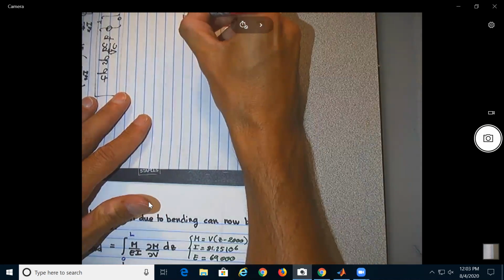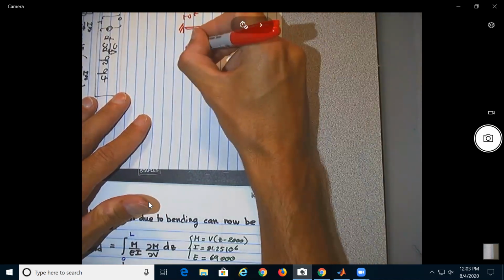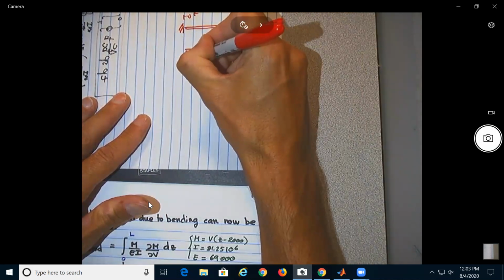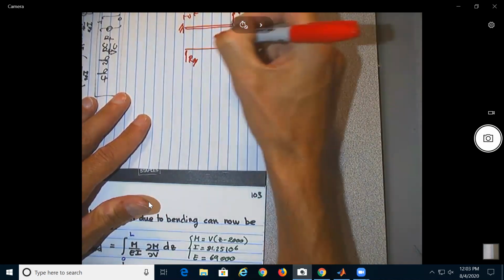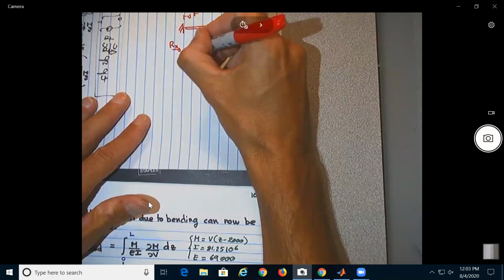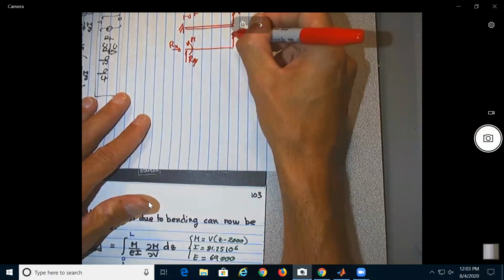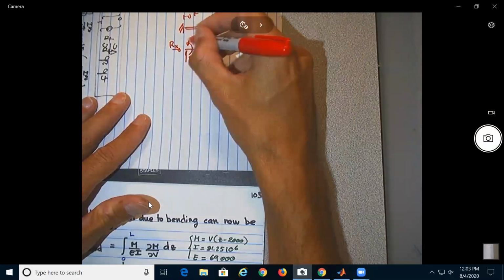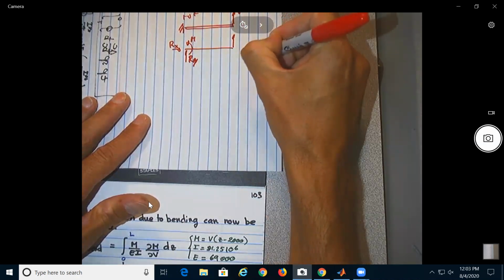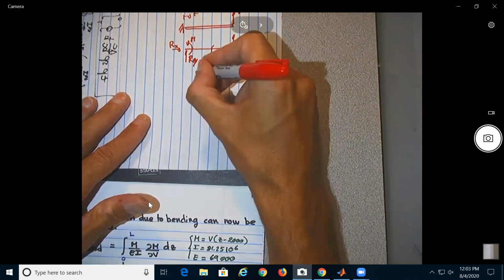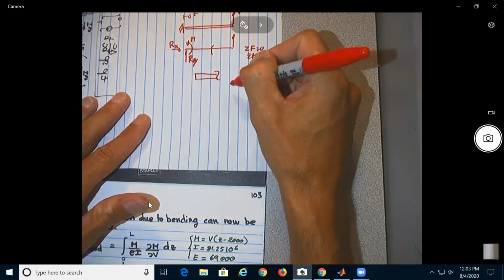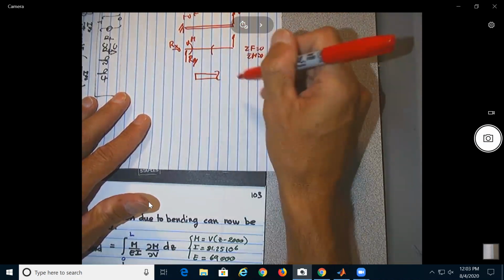You will have to say that here you have your force V. Here you're going to have a reaction R, let's say RY. Rx here will be anyway 0, and here we'll have a bending moment at the root, no? You find this by doing summation of forces, summation of moments, and then you take here and you need to make a cut to make the internal forces become external.